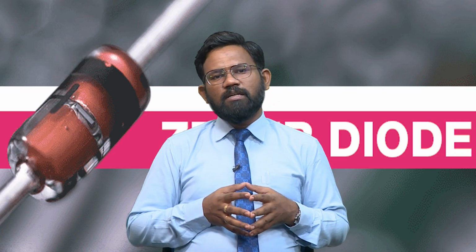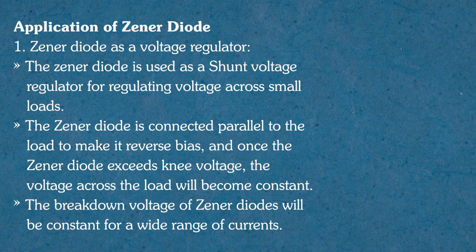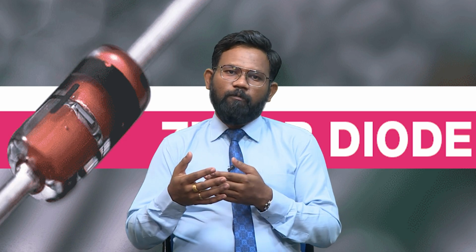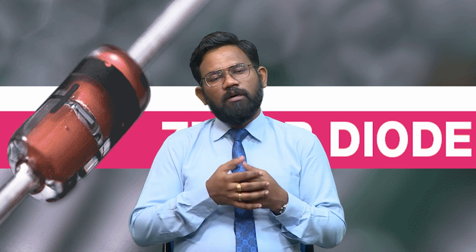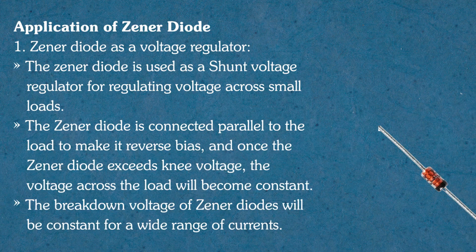Now, let us discuss the applications of Zener diode. So, Zener diode is a very special kind of diode. It is used for various special applications for which the normal or ordinary p-n junction diode is not suitable. So, the first application of Zener diode is as a voltage regulator. The Zener diode is used as a shunt voltage regulator for regulating voltage across small loads.